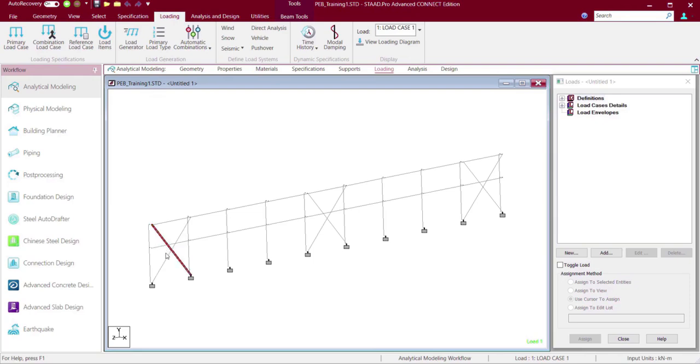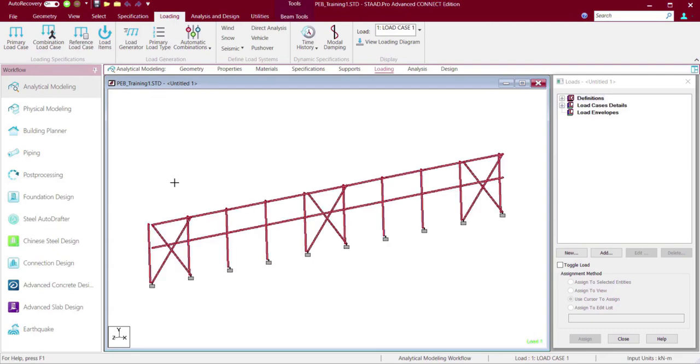So just select the plane, where you can specify that these are the areas where the wind load is going to hit first. For example, I don't want these bracings to be considered for experiencing the wind loads. I want my external sheeting or the facade to rest on those purlins and those web members. So I want those wind loads to hit those members only.